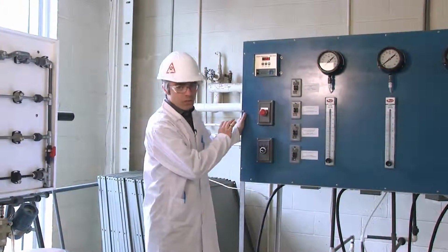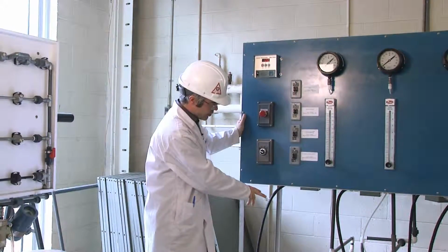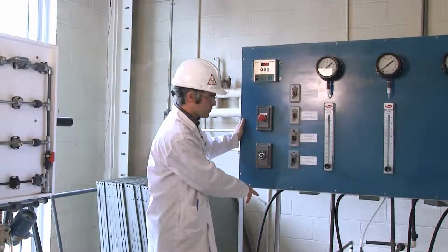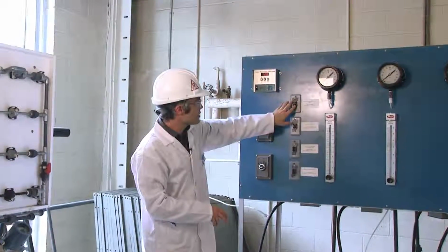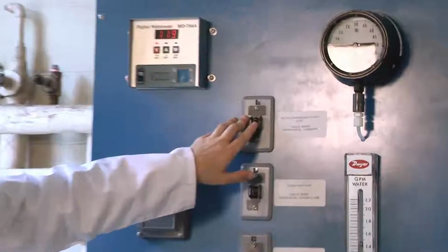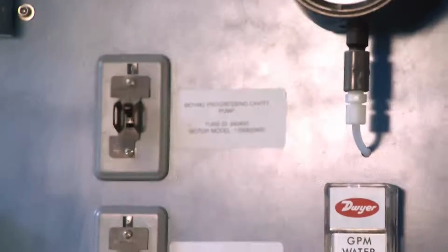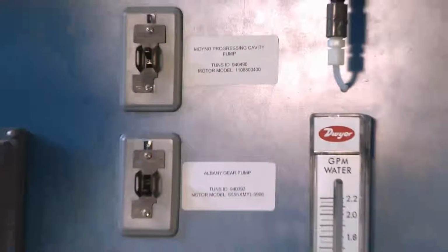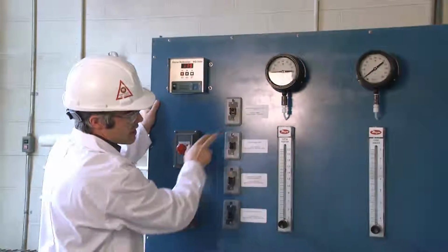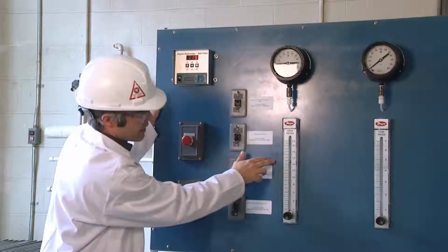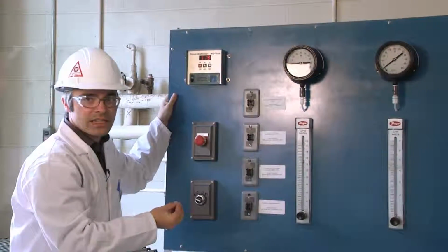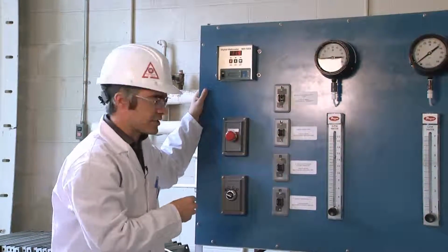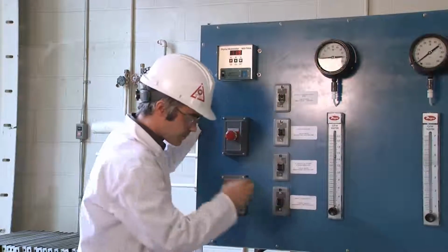Once we've checked that there is water within the system and the valves are open, we can select the first pump, which is the screw pump, and we will turn it on here. As noted in your laboratory manual, for the first two pumps, it makes more sense to choose the pressure and look at the associated flow rate, and to choose multiple pressures in order to fully characterize the system. The reasons for this will become apparent as you begin to adjust the flow rate.